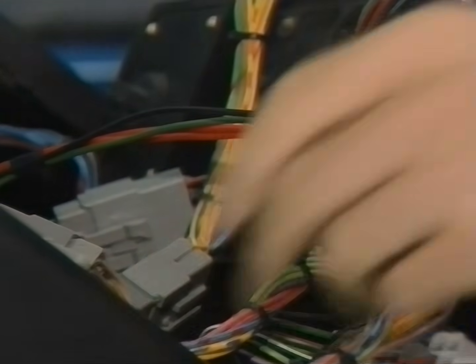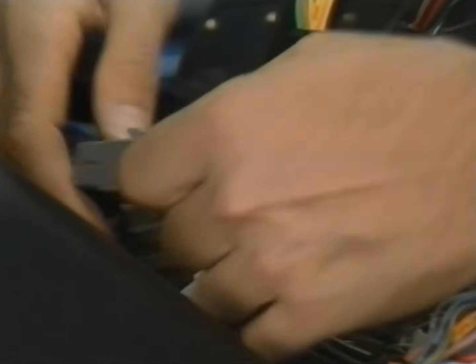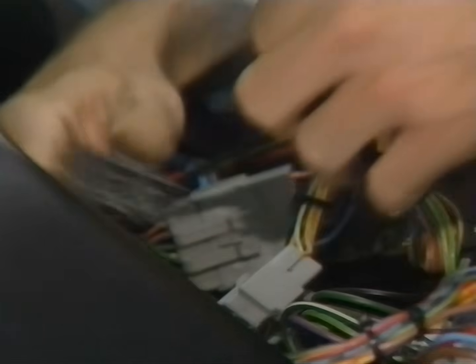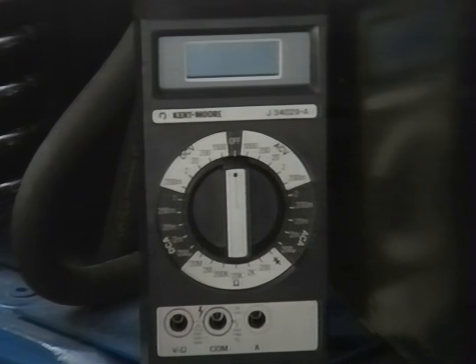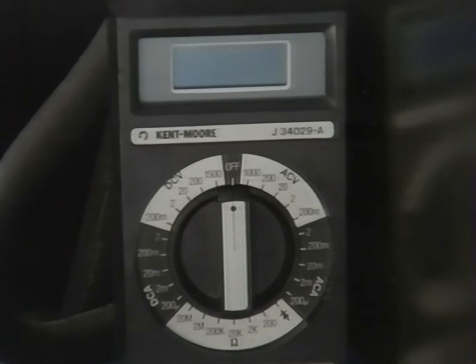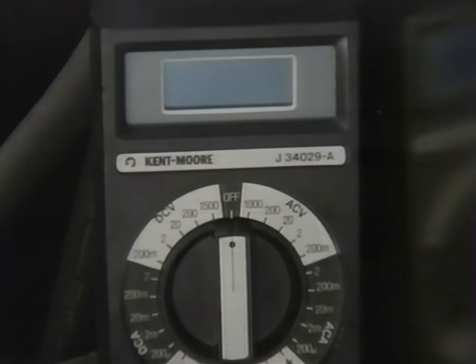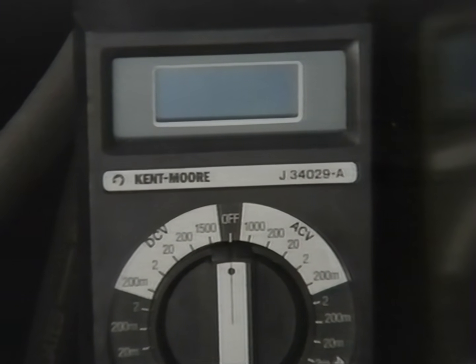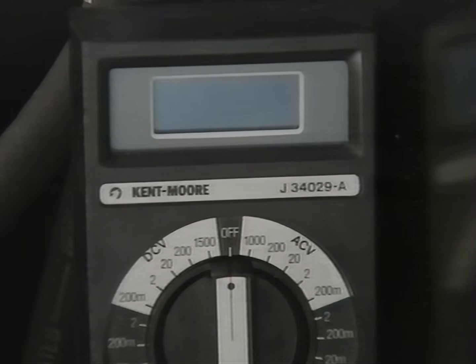These include isolating the EIP from resistance checks made on switch or sender circuits. Resistance checks may damage the sensitive electronic circuits in the EIP. When checking circuits, be sure to use a good multimeter that has an input impedance of at least 20,000 ohms per volt. This helps protect sensitive circuits.